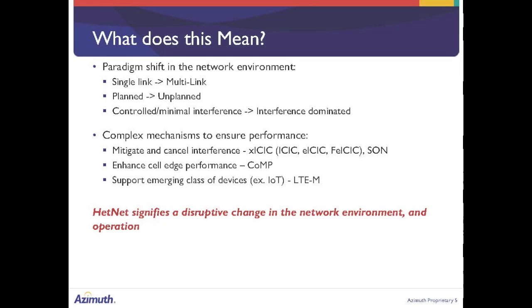So now let's look at, on the device side, how is this all being handled? Well, advanced interference cancellation receivers is the answer. Initially, in release 11, they developed the performance specifications and the standard receiver model for the so-called interference rejection cancellation receiver, which does its work by not simply assuming that everything that's not signal is white noise.